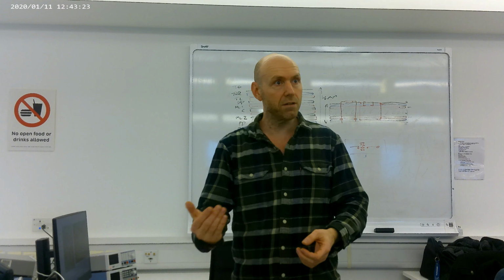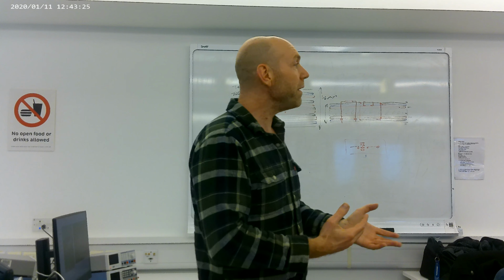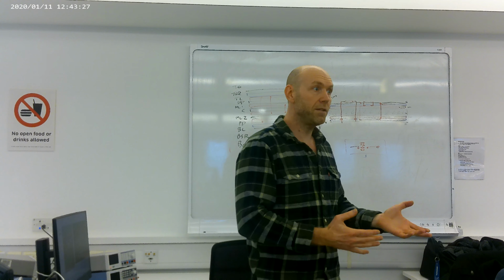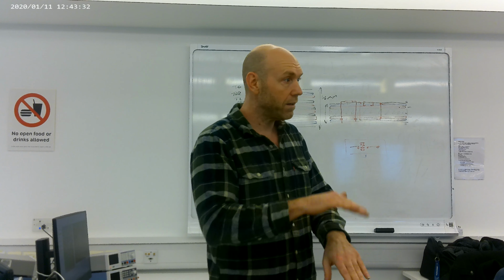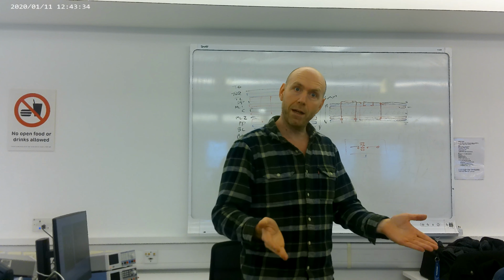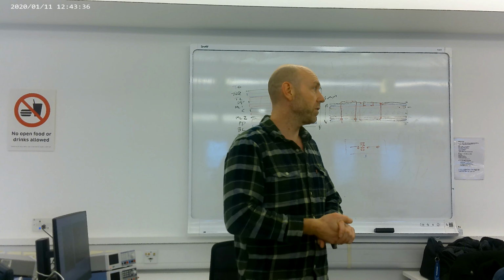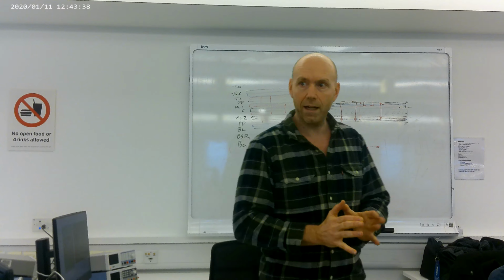the maximum current that's going to go through there, and you would use a PCB calculator like Saturn PCB calculator, it's a free download, where you can put in the width of your track, the height of your track, and it will tell you the maximum current that it can pass through safely. Yeah? So you've got to understand that.